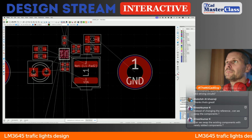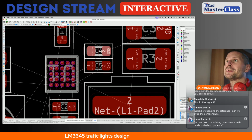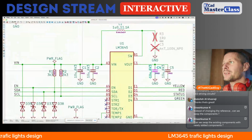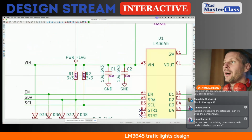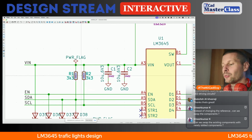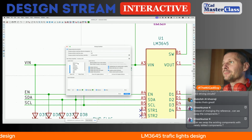But let me say something. When there are 0402 components, all the capacitors are 0402. Why not place 0402 as well, to keep a balance?